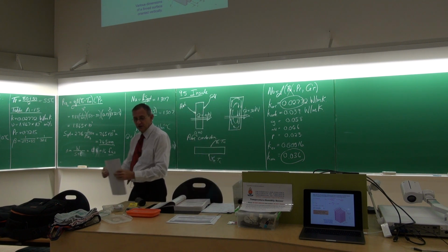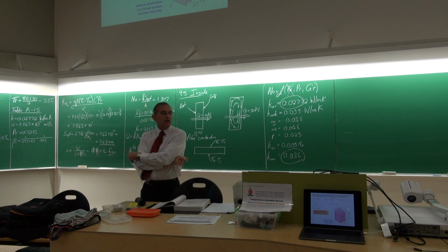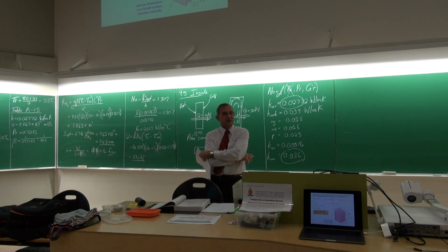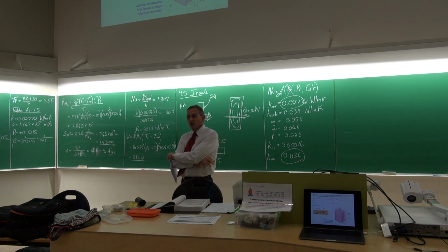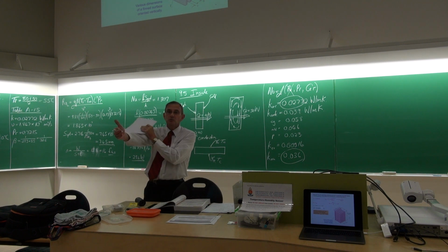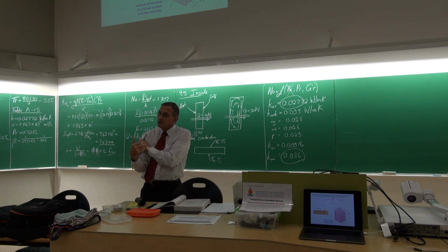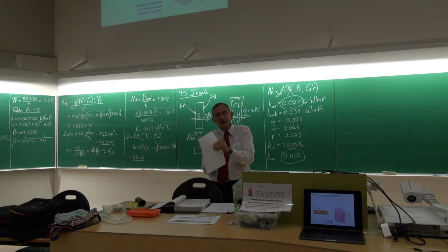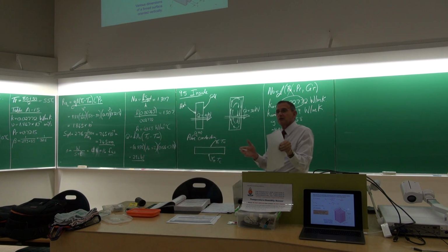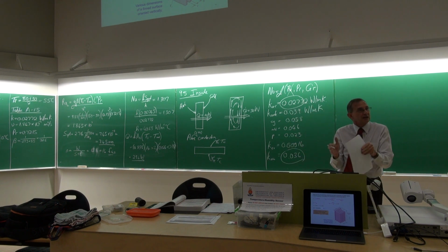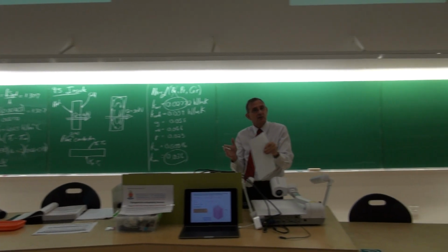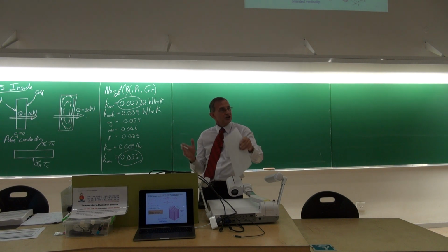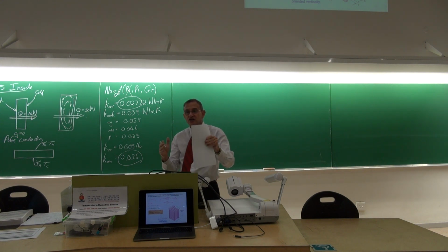Fortunately, we are very fortunate that air has such a low thermal conductivity. Otherwise, if there was a fire here, you would burn yourself. The air is a natural insulation material between you and the fire. And the result of that would be that the only heat transfer that you're going to get in most cases is the radiation heat transfer. It is not going to be the conduction or the convection.